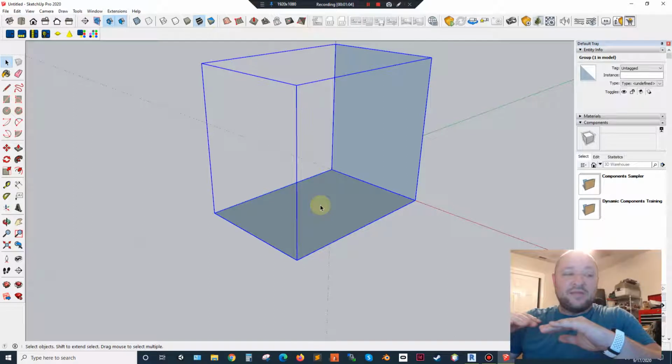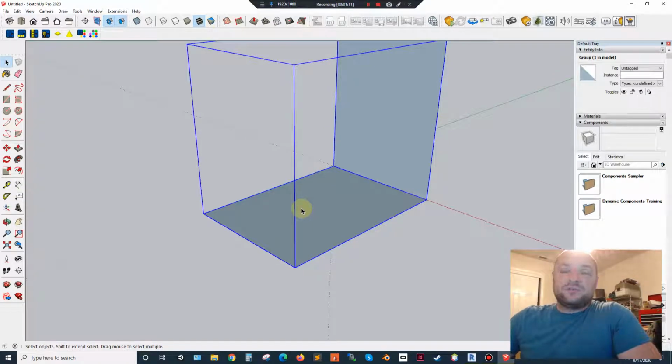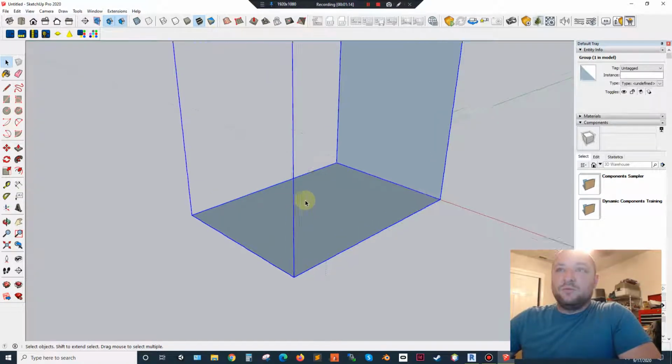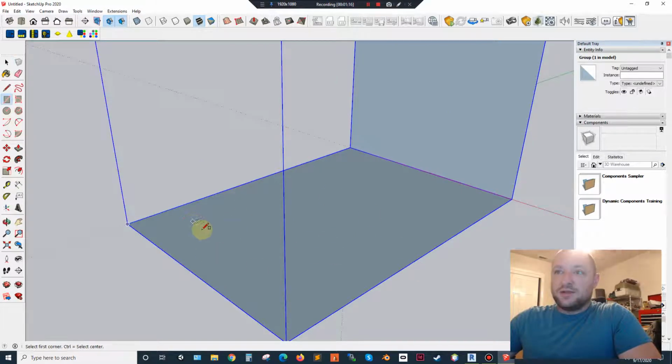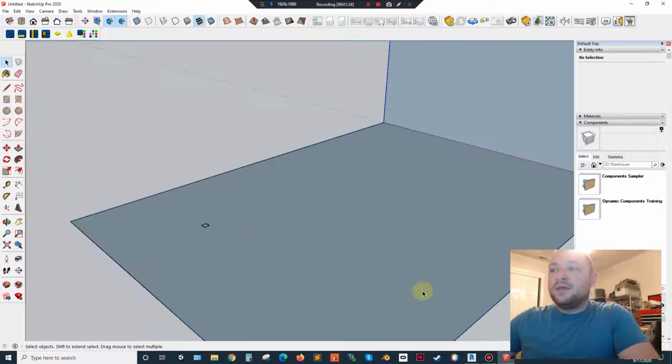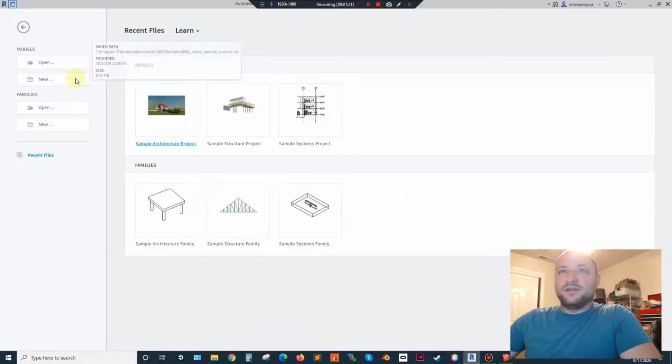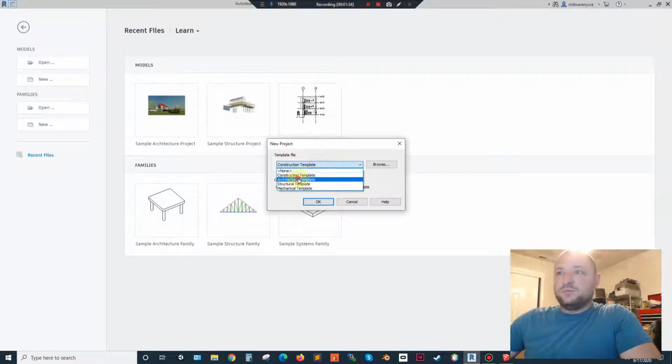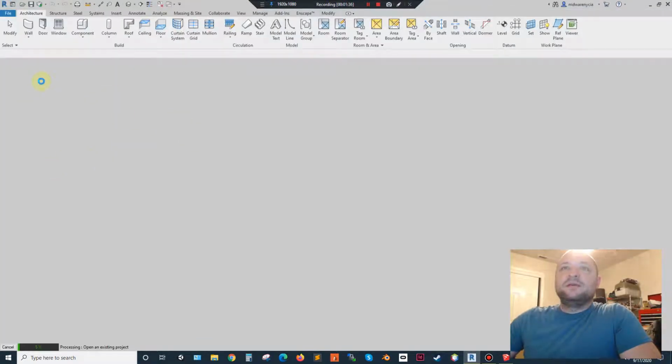What I'm going to do after that, just to kind of mix things up, is use a secondary plane. So when we're working with the extrusions in Revit, what you need to visualize is this is 0 right here. So if I have a small rectangle here, we'll just do 1, 1 for a 1 inch square. I'm going to turn my video off there so we can see what's going on. Let me hop into Revit here, and I'll get Revit caught up to where we're at there as well.